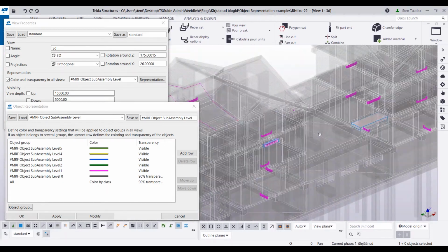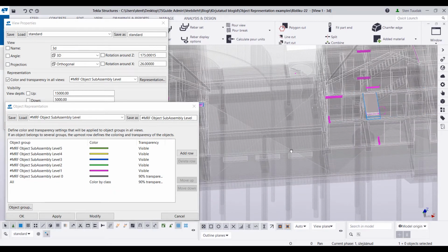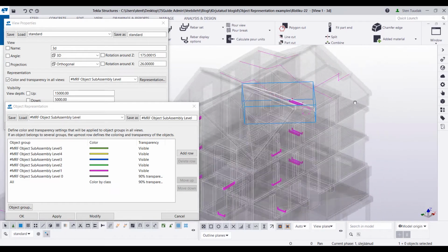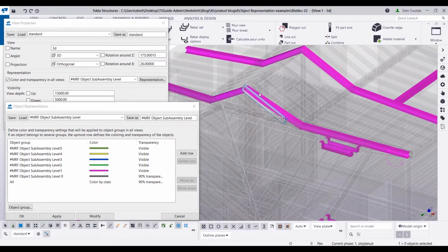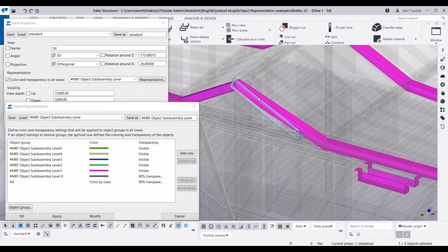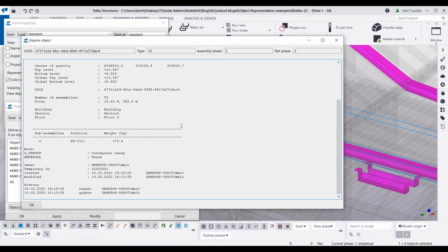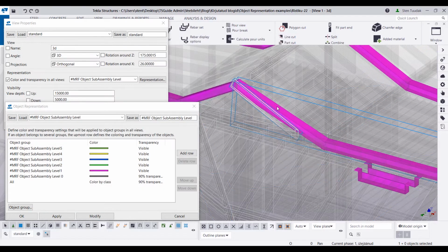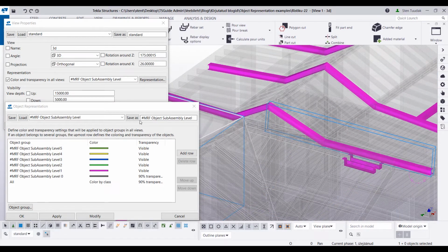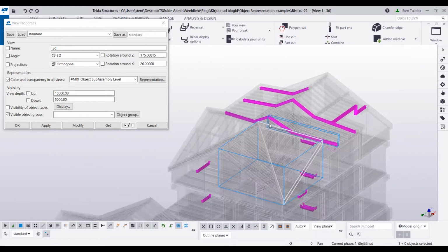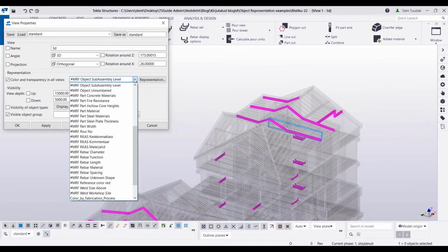They should be attached as parts only, but maybe in this case it's not a problem. The problem can come with these beams that have been attached as sub-assemblies, and then the problems come mostly in reports and drawings. So they are sub-assemblies, but they should most probably be attached just as parts. But at least we can then decide how we want to do it.